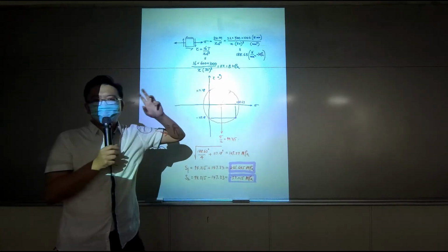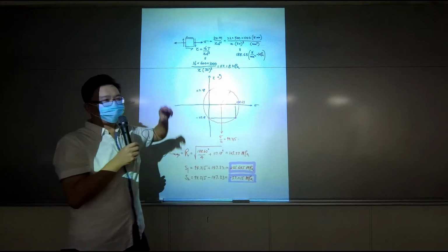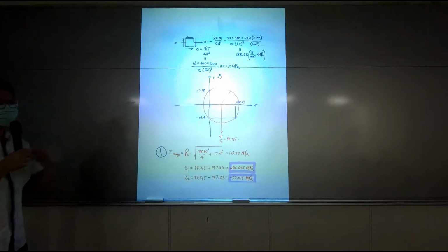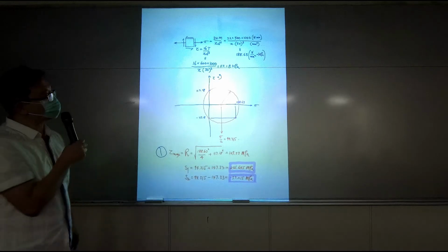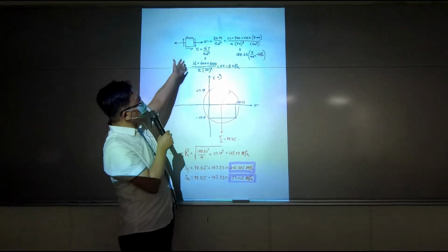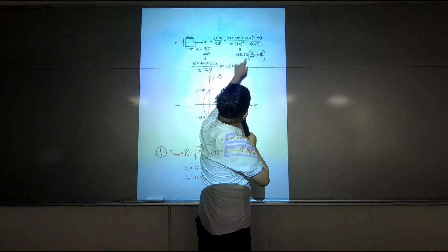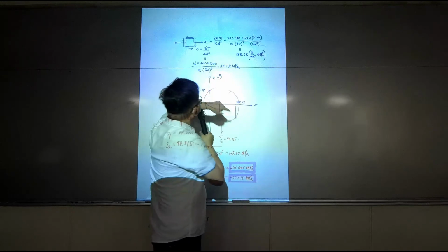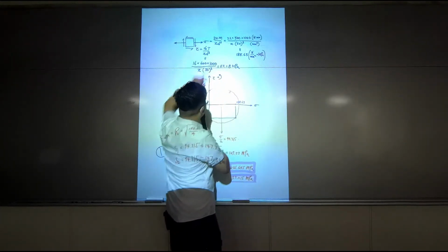So whenever you use an equation, you must understand, can I use it? That's the most important thing. The next thing you need to do is be careful on solving. Just plug in everything, you get 188 megapascal for the normal stress. You get 113 megapascal for the shear stress.